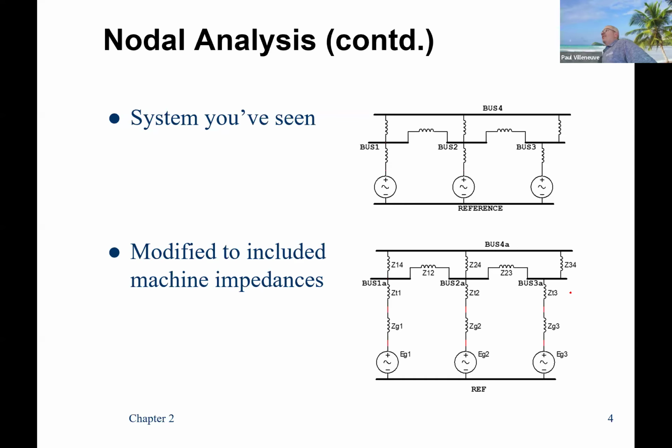That's exactly right. Is there such a thing as an ideal voltage source in the real world? Does everybody know what an ideal voltage source is? You put 12 volts on it, or let's say it's rated for 12 volts, and an ideal voltage source will maintain 12 volts regardless of the load on it, including a dead short circuit, right?